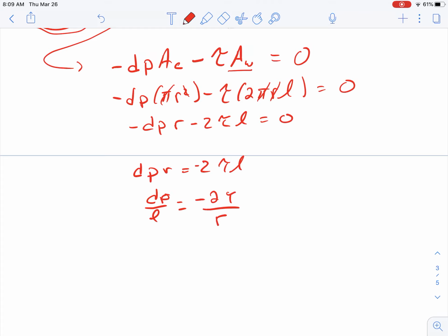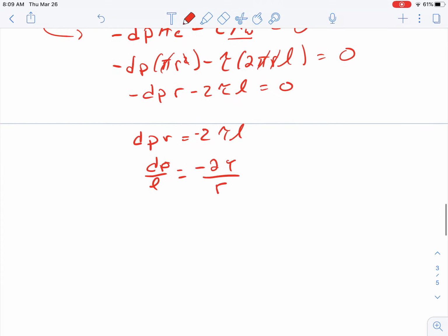And this is, if we think about this as our pressure drop over some distance L. Remember, we were looking at in the pipe entry length, we had an entry length that came down non-linearly, and then the curve went straight. So this is some length L along the pipe, and let's say that's the length x along the pipe as we're moving along.